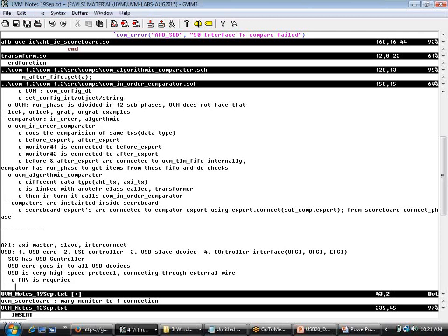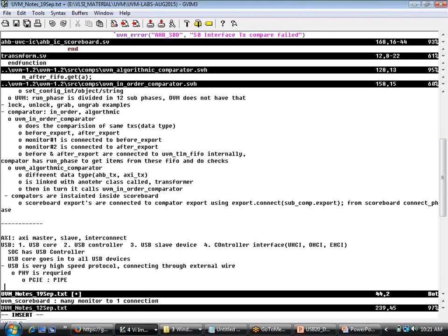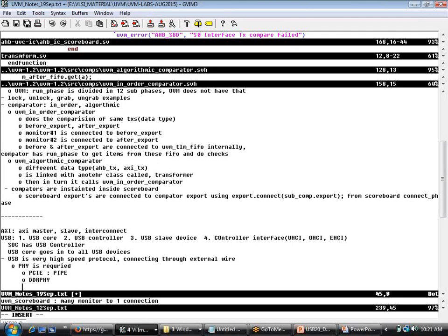In the case of PCIe, that is called the PHY Interface for PCI Express. Same way for USB, it is called UTMI, the USB 2.0 Transceiver Macrocell Interface, meaning transmitter and receiver macros. The I means interface, but it is the UTM. This is equivalent to a PHY.